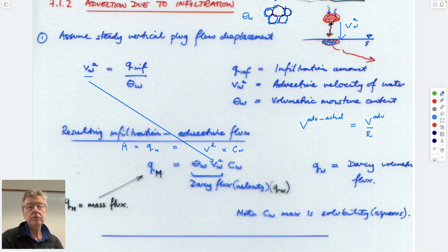As it goes through the soil, it should go at this velocity. This is what you've calculated from this. This is just a physical term. But it's going to get sorbed onto the matrix, and then for it to be delayed, just like the plume is delayed elsewhere. And so, here's a good question. Is this the aqueous or the gaseous retardation coefficient?